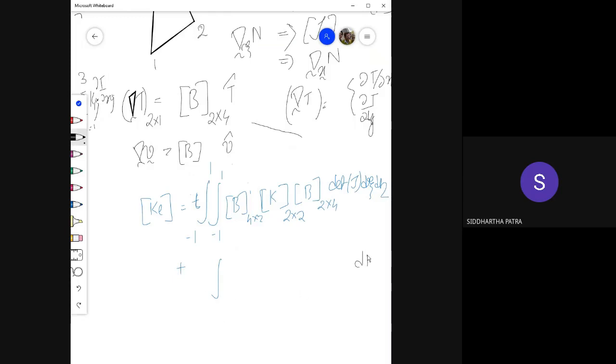So there is d gamma, and basically you have h times N transpose N d gamma, which would be a part of your stiffness matrix. From the left side V hat transpose is multiplied, from the right-hand side T hat would be multiplied, but then T hat multiplies every term in the stiffness matrix.